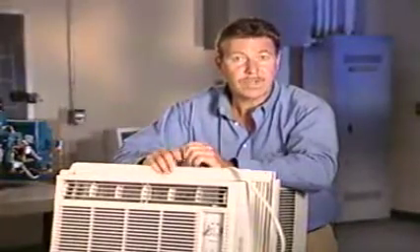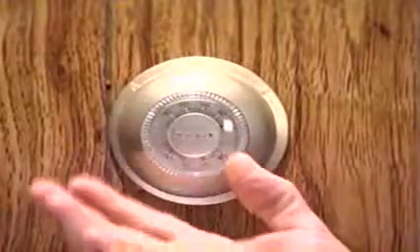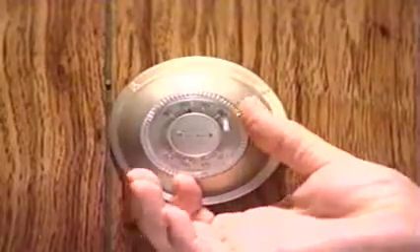Thermostats can be designed as either line voltage or low voltage devices. Line voltage thermostats are designed to make and break line voltage circuits and can be found on such systems as window air conditioners or electric baseboard heating. Low voltage thermostats are commonly found on residential central air conditioning systems, as well as on most commercial and industrial systems. Low voltage thermostats are desired because they are typically less expensive than line voltage thermostats and are safer, since the voltage in the device is lower than in the line voltage version.